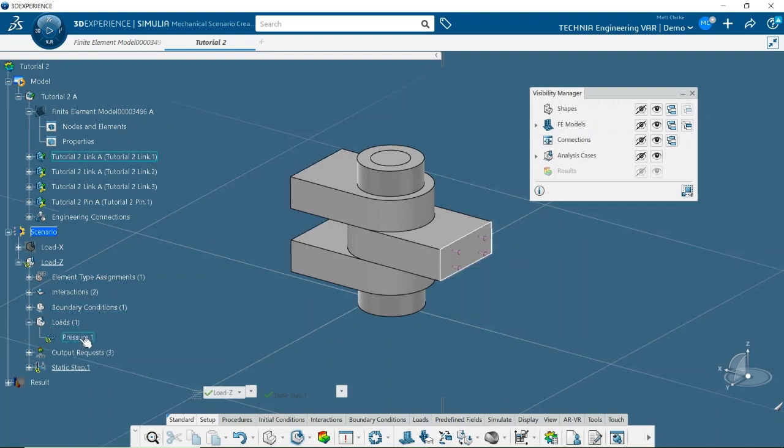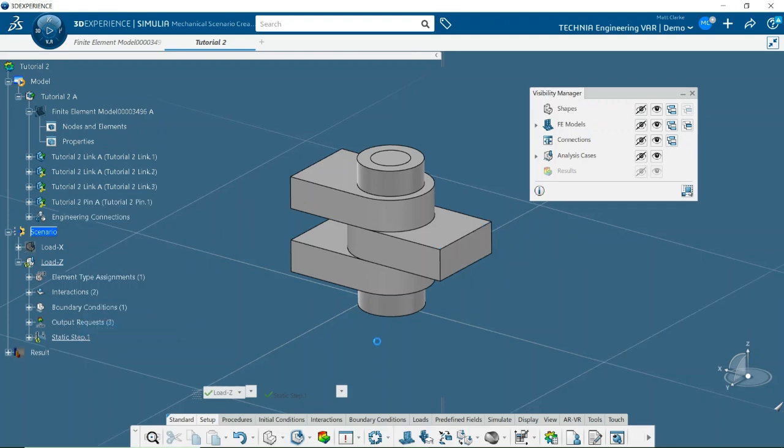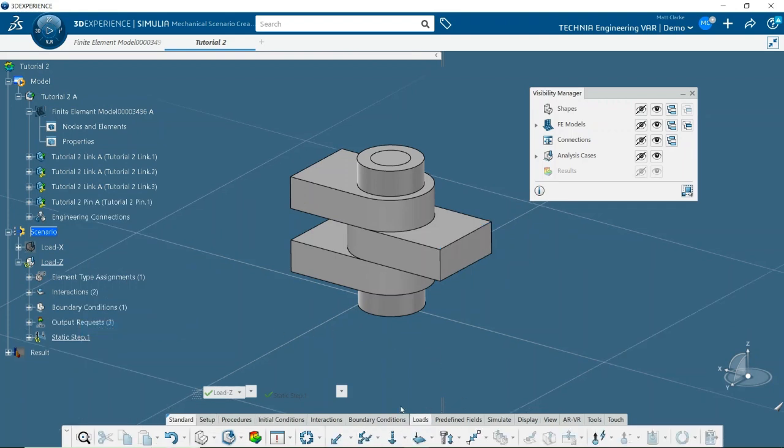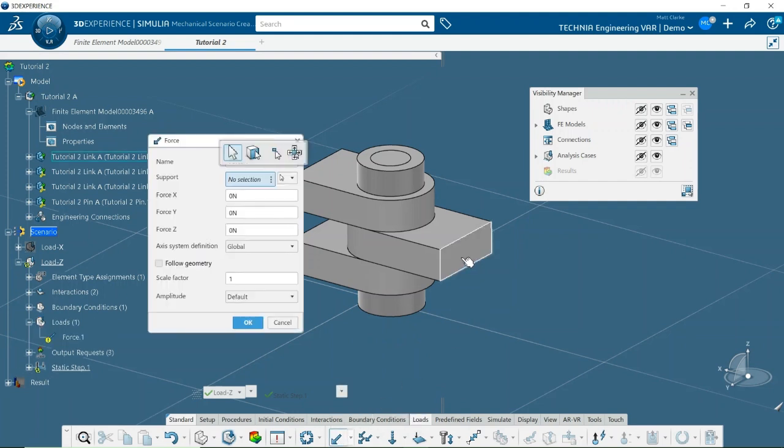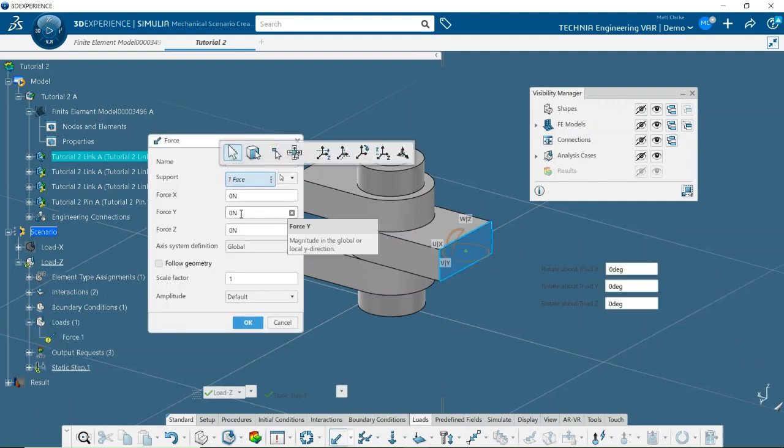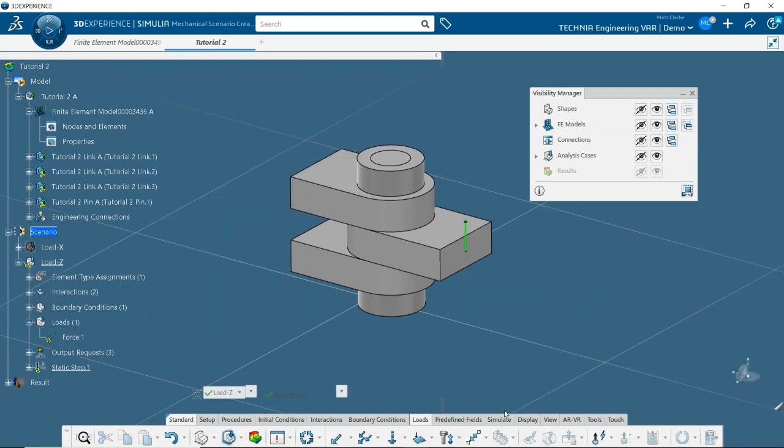The load type isn't quite correct for this. So I'm going to delete that pressure load, come back and put a different pressure load on here, which is going to be a traction type load. And I'll do 150 kilograms force acting in the Z direction for that. When I click out here, we get a glyph to show us the direction. That's OK, and that's all complete.